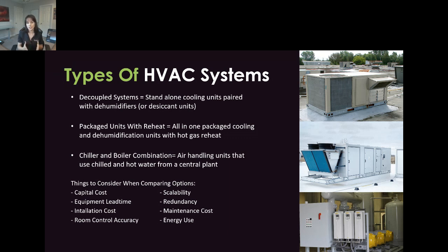Our units, as I said, are packaged units with 100% hot gas reheat capacity. This means all of the cooling and all of the dehumidification is done in the unit. And based on the configuration of the unit, we are also able to get free hot gas reheat.